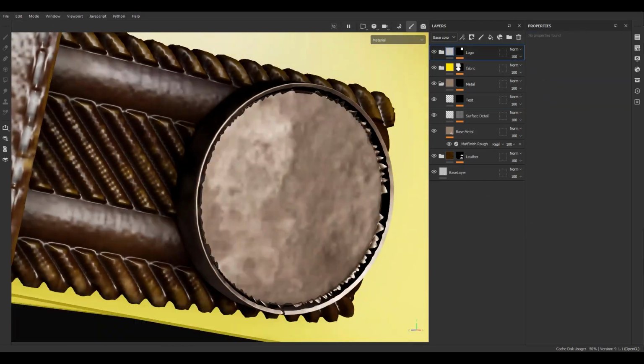And my idea for solving this problem is to create a mask for my detail and invert it and give a positive height amount to that inverted mask. In this way, we are just keeping the surface at the default height value, and for the other part, we are just going to push out. And in the push out effect, we don't have this kind of problem.